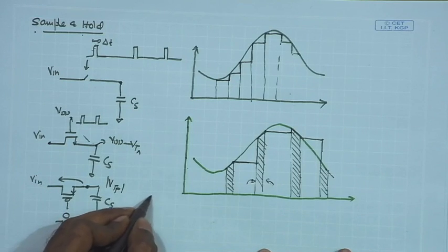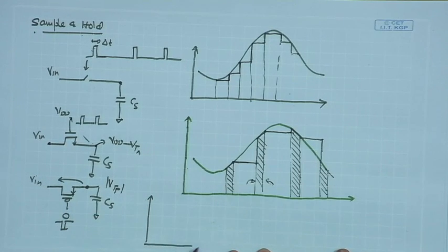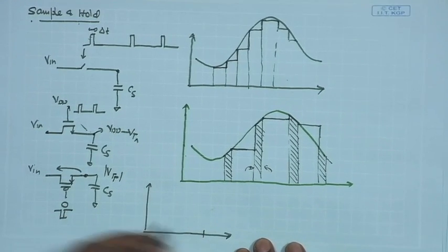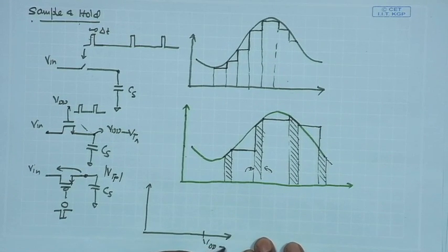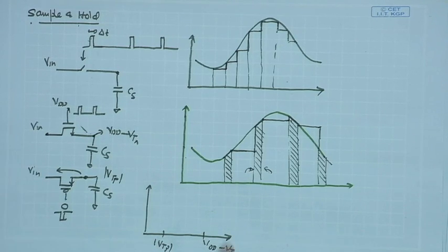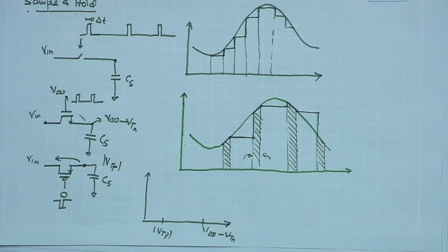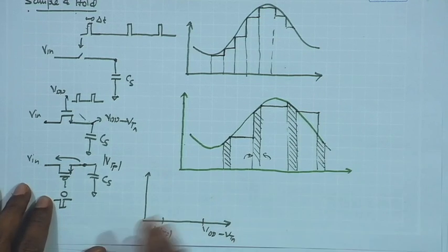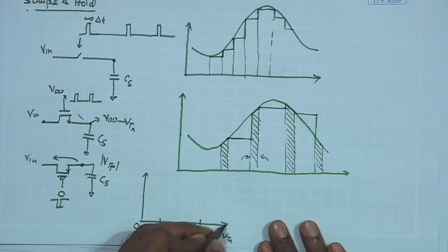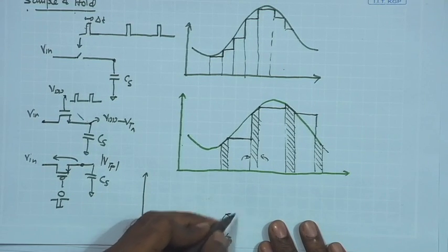So, if I plot the resistances of this NMOS and the PMOS switch, we have the curves. If I mark this point as, say, Vdd minus Vtn and this one as mod Vtp, how does the resistance of the NMOS switch look? The input, as we have seen in our case, can go all the way from 0 to Vdd. So the input can range from 0 all the way close to Vdd. This is the point Vdd.